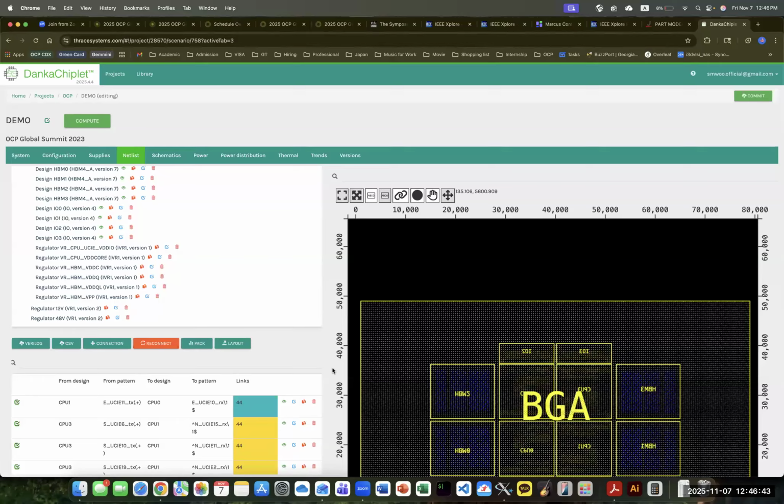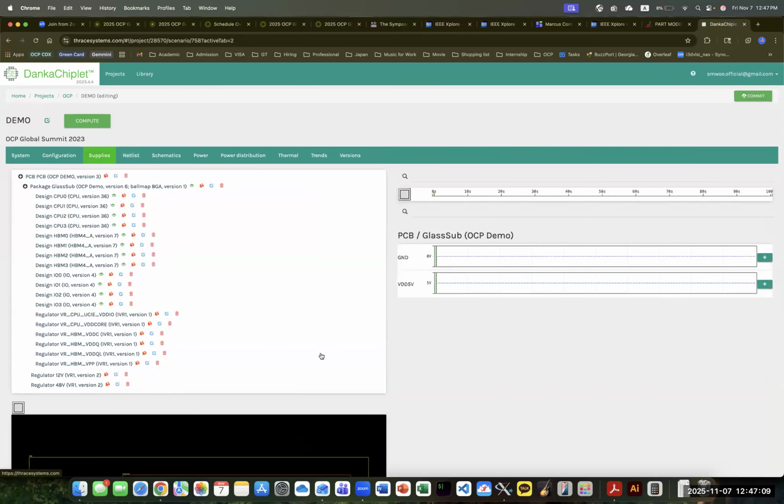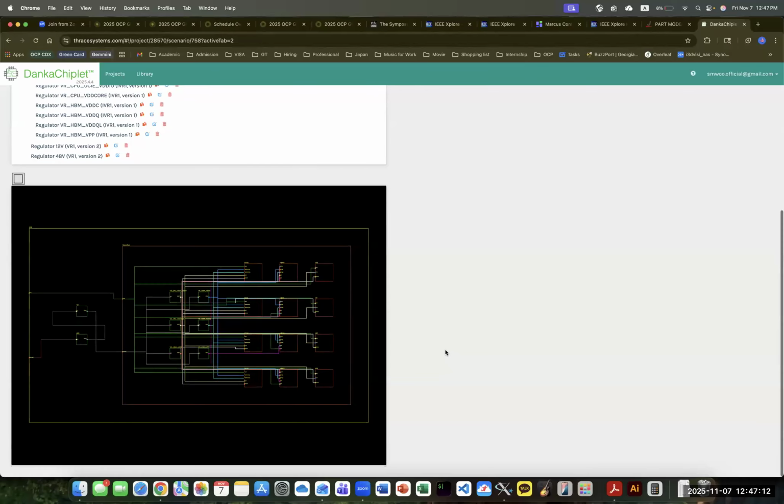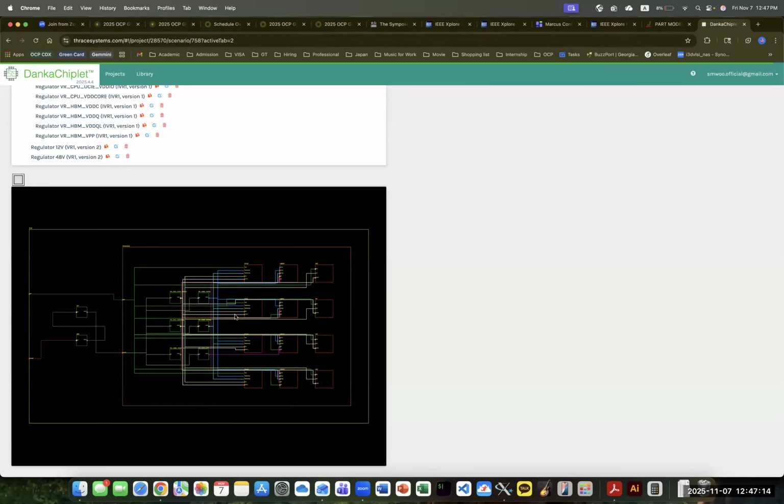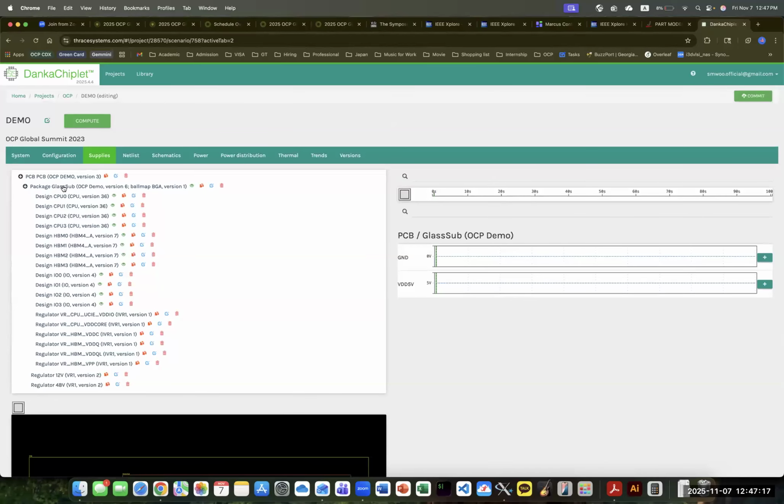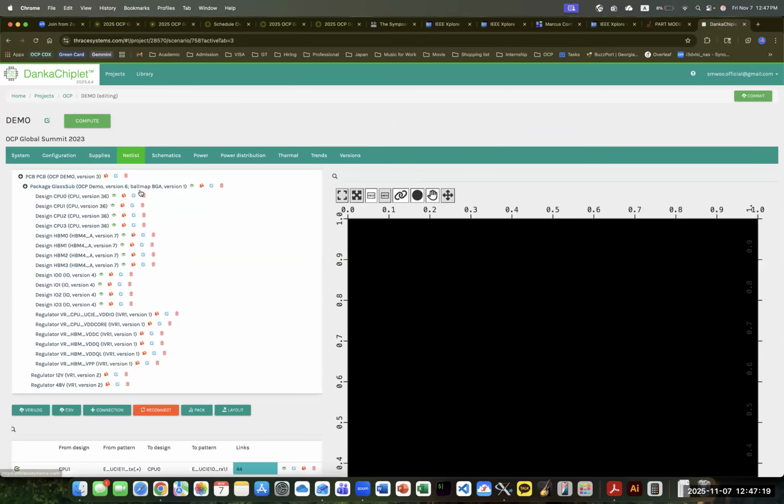And all the power to all the silicon up top is coming through glass interposers, right? Say it again. Which power? All the power for the chiplets is going to come from the bottom, through the interposers. TSVs, I'm sorry, the TGVs. Yes, glass interposers. And then the IVR input power is going to come from the bottom. Right.